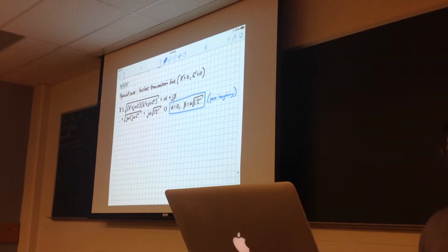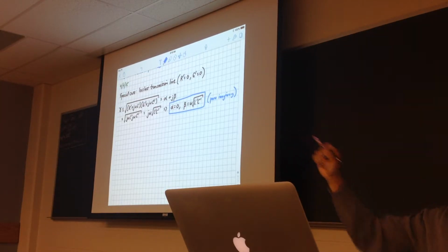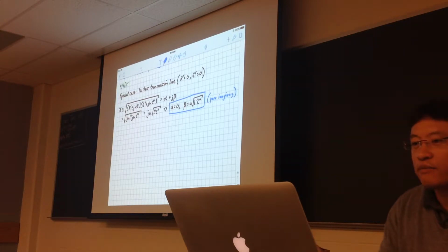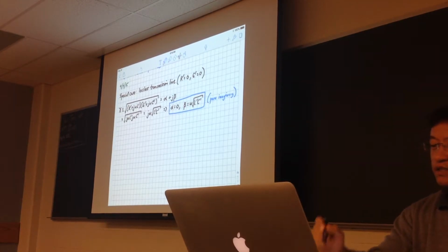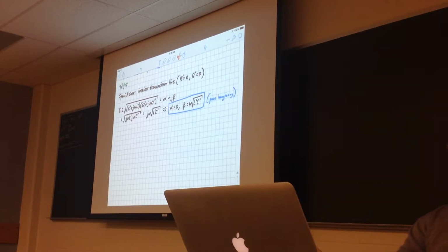Which is why we say alpha is representative of the loss properties of the transmission line. That's why we call it the attenuation coefficient. And if there's no loss, then alpha is 0, no attenuation. The signal traveling across the transmission line from one side to the other will not experience any attenuation, no loss, as it goes across. Okay, beta, we will see, is going to be related to the wavelength as you propagate through the transmission line. We'll save that for a little bit later.